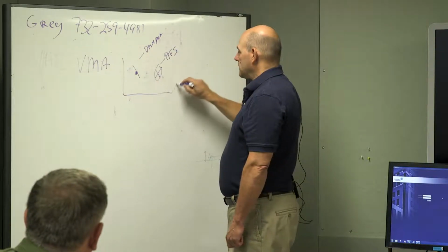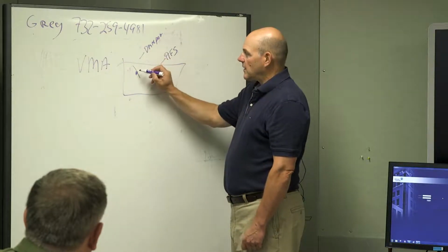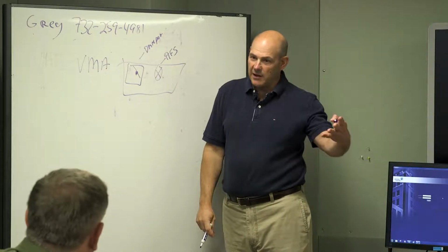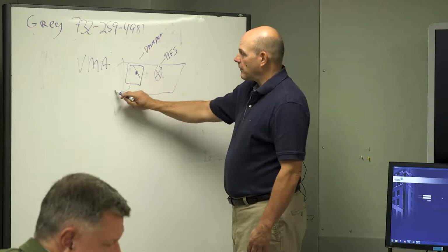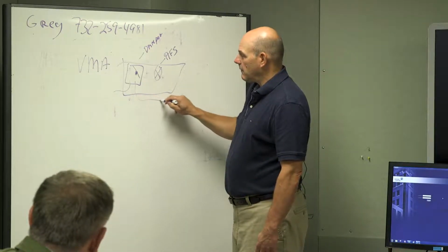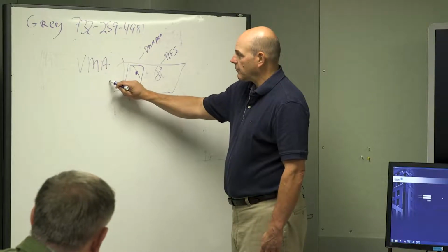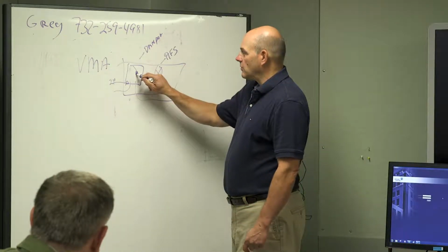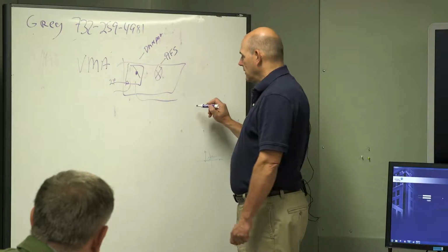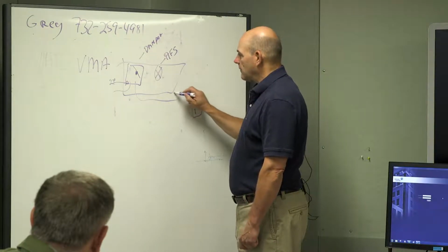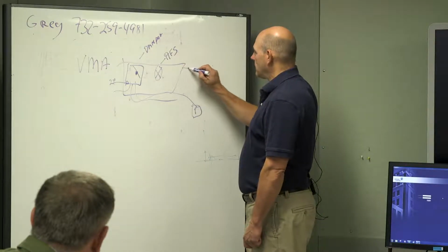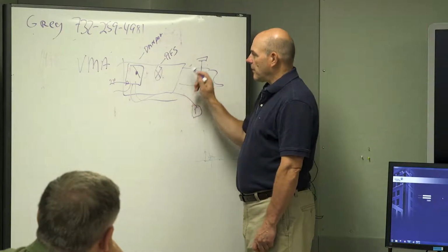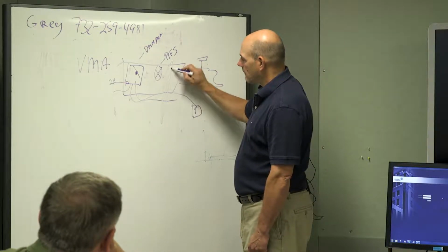And that just comes in a big box, and we call it a VAV box. What we slap on this shaft is a damper motor and a controller. It's got the brains of the FEC. So we wire power to that and network. So here's your power, 24 volts, and there's your network cable. This controls the airflow in the box. So you have a temperature sensor in the room that gets wired to here. Then you also have, here's your ductwork, and then you have a temperature sensor here to monitor this, and then you're gonna have a coil with a valve.